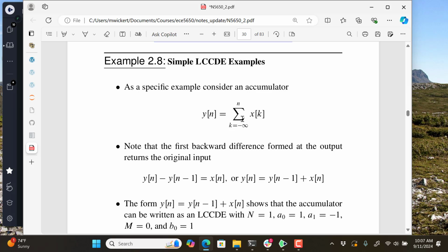And I'm going to refer you back to your earlier exposure to the integrator for continuous time systems. Is an integrator stable? If you happen to put a DC value into an integrator electronic circuit, what does the integrator do? It just starts ramping, positive or negative. It hits the dynamic range of the electronic circuit itself, like the op amp, and it flattens out. In DSP, the accumulator here can do the same thing.